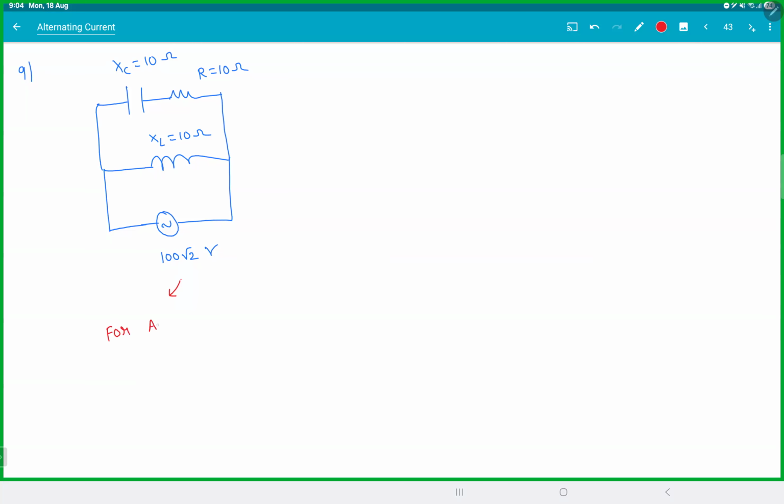And how do you need to solve a DC circuit? Look at the symbol. There's an AC symbol. If you actually wanted to say DC, then your symbol should have been like this. Then I'll assume it is a DC battery. You gave me a round symbol and you're telling me constant. So for an AC source, if a constant value is given, it is an RMS value.